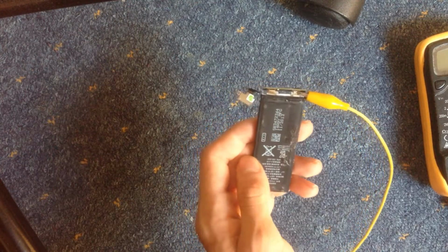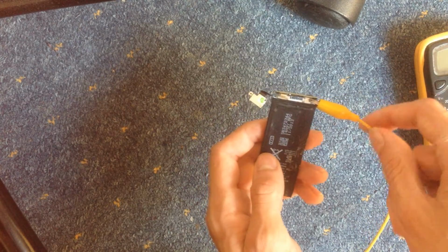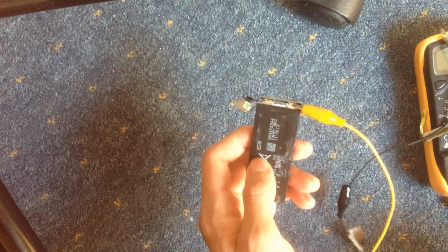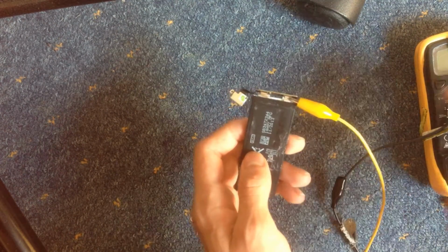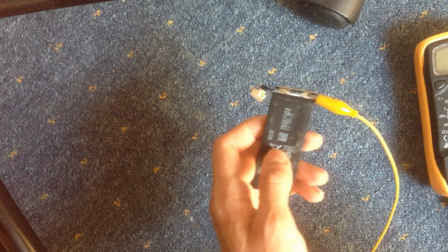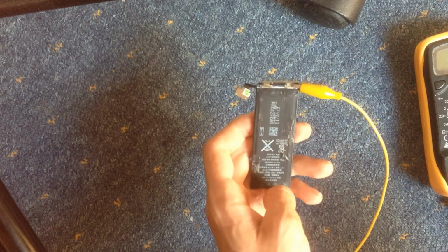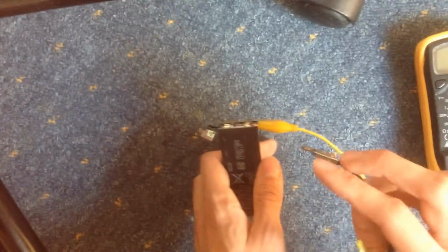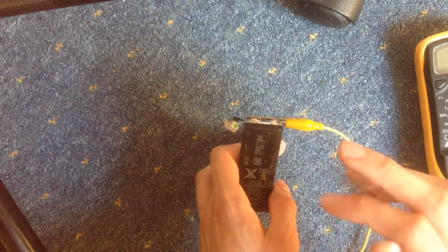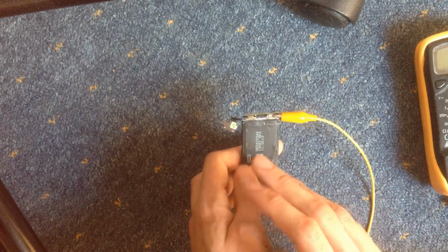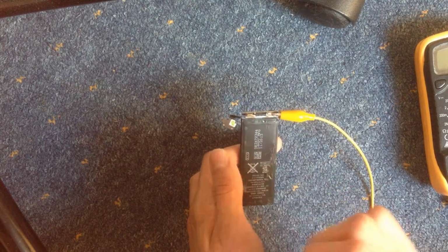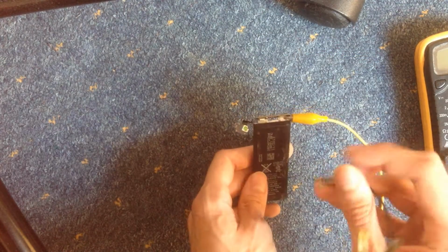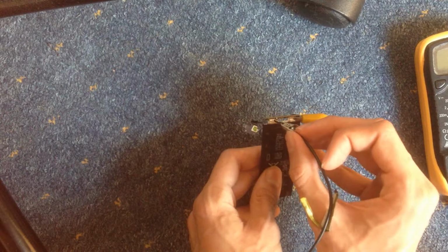Okay, so just use any kind of cable, but do not use those original ones, because they got iron wires and they are pretty bad, because the resistance of those is too high to really short circuit this battery. And with this part, just be really careful. You just have to short circuit for like 1 second, because it's not good for the main battery cell to do it, but it will just basically reset this part. So let's just quickly do this.